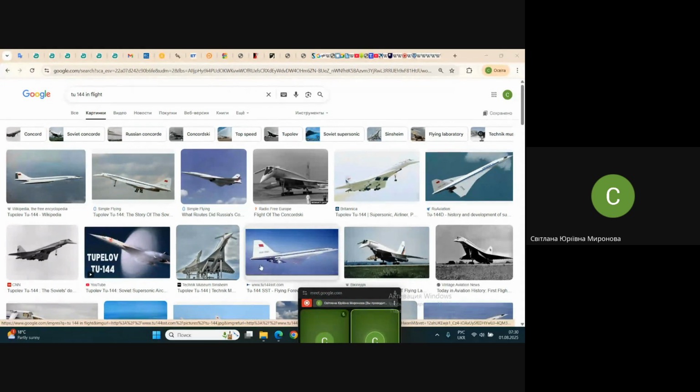Here you see the straight nose. Four engines are visible. The intake holes are also of rectangular shape, and they are visible in that photo. There are four intake holes, and it means you have four engines. They are under the airplane. You see the intake holes here under the wing, and the engines are practically behind the passenger cabin, under the airplane, and the nozzles are not far from the trailing edge of this airplane.